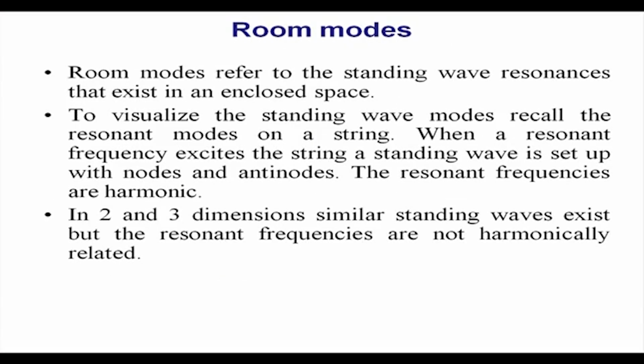I am not discussing that now. If it is a small room or a large room, we have already discussed. For large room acoustics, we can treat the acoustic wall to control the reverberation time. I know the reverberation time, I know the volume. So, I can treat that wall with a different absorption coefficient to calculate and reach the desired A in T.